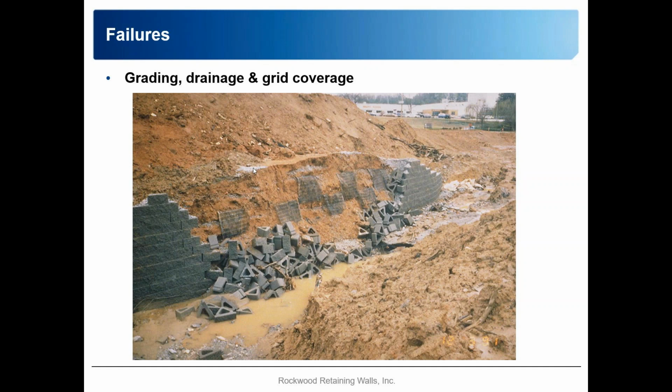In this case, you can see the contractor put some geogrid in and then skip the space and then put another piece of geogrid in, then skip the place, put another layer of geogrid in. This needs to be continuous. So this should be a continuous layer of grid. The geogrid is actually coming out of the face and just is laying flat.